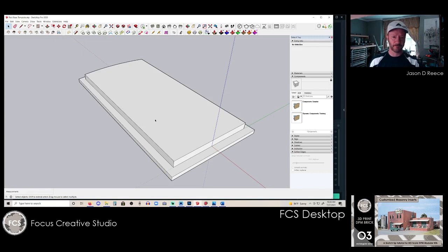So we're always pulling the face we want the most and highest detail to the top of the print. Anything you put on the bottom can tend to have pimple marks because of how the resin system works. It's dropping in, pulling out, dropping in, pulling out. That resin isn't always flowing completely away. So when the light kicks on, sometimes there's a little bit of light bleed that cures some resin on the bottom of your prints. So we just want to avoid that hurdle with the parts that we want to be pristine. They face up on the build plate. So that's what you have here.